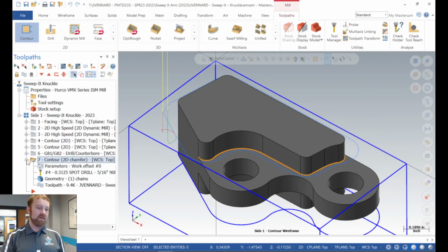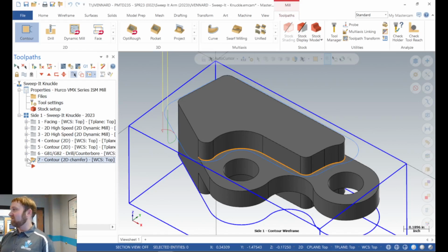The things that I repeat and talk about up here, it's because I see it all the time. Kind of like the other day when we went to side 2. I had people say, hey, it's giving me a travel limit error. I had to remind a few people, I can't remember if it was this class or Mondays, remember we use G55. You've got to go in and put your offsets in G55. And I know I talked about that when we were programming it.